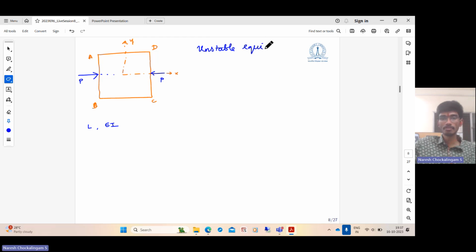In my last session, I looked at the aspects of stability of structures. And what did we say? An equilibrium configuration essentially means all the forces and moments are balanced. But how stable is it? The question of stability of equilibrium has to do with small perturbations about the equilibrium configuration. Suppose we have a column subjected to equal and opposite forces, and you give a slight deformation to the column. Is it stable enough? Would it deform uncontrollably?